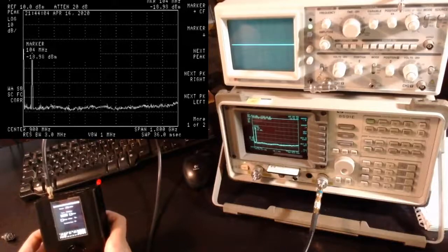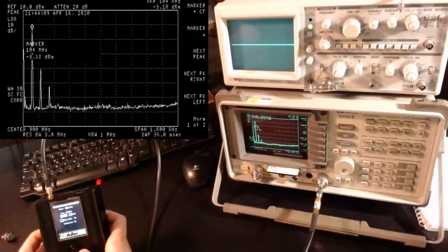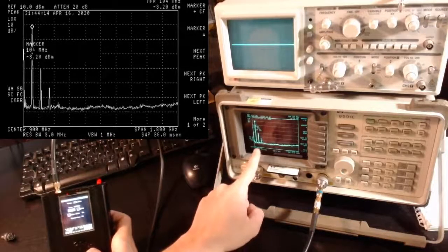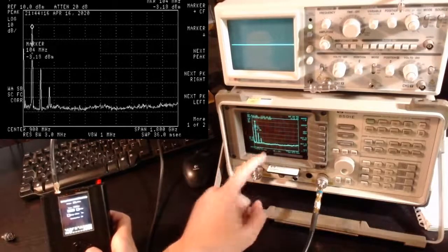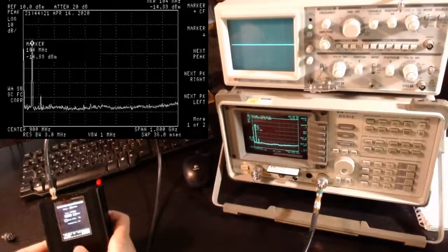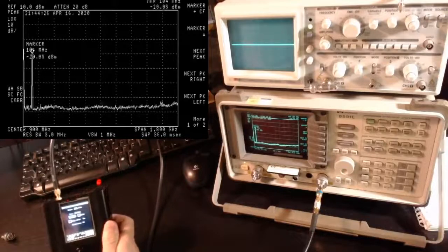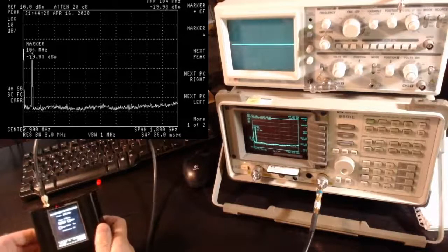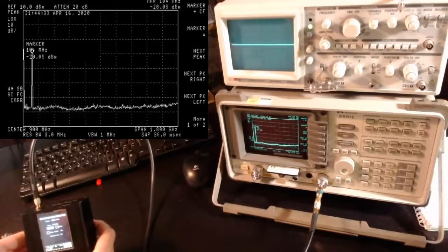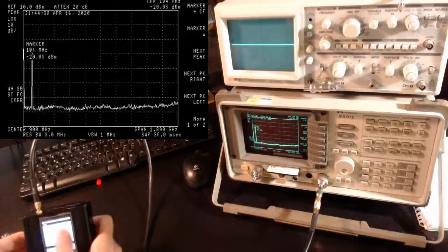But if you go up with the gain, as before, we start to have very bad side harmonics. So at the moment we're at 40, it's probably not worth going above 26. At the moment we are at 26 and the signal is pretty clean. We do not have any harmonics. So let me try to go to, let's say, just to make an experiment, 500 megahertz.